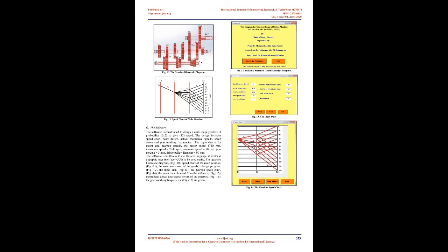The small deflection theory is applied, the system undergoes a linear elastic material behavior associated with the damping effect via ignoring the nonlinearities. The applied load F and its response X have a sinusoidal function at a given frequency. All frequency response spectra are obtained and analyzed. The sample is shown in Fig 9, which shows the frequency response functions of the original and modified structures in the Y direction. It is helpful in dynamic analyses of the milling machine.